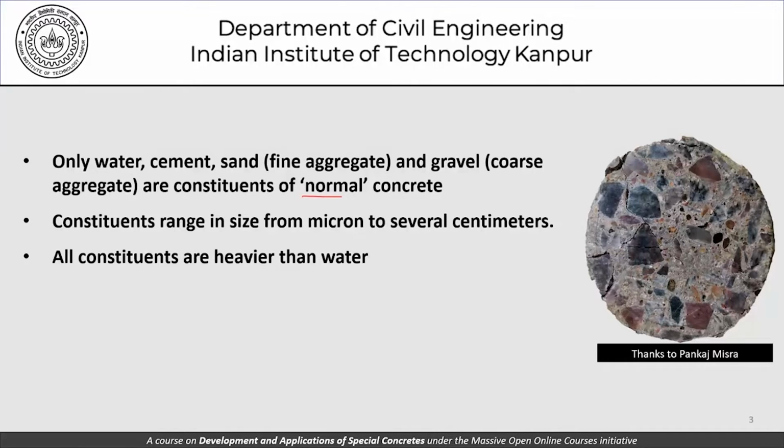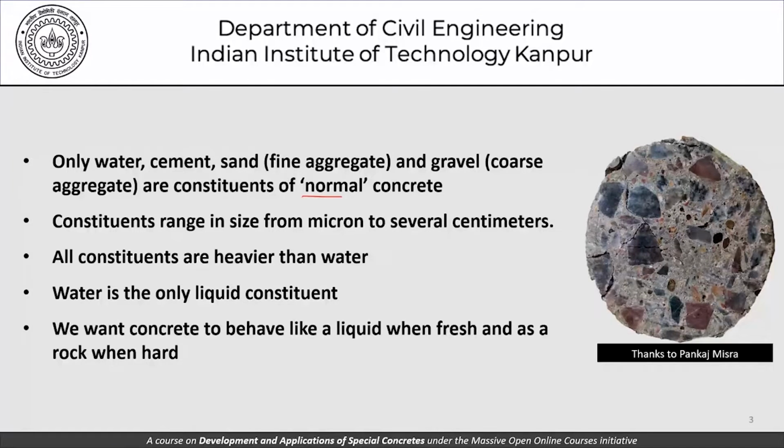All constituents are heavier than water. That's something which we must keep in mind. Water is the only liquid constituent, and that's the only thing that really brings about the workability, the flowability part of concrete. We want concrete to behave like a liquid when fresh and as a rock when hard.